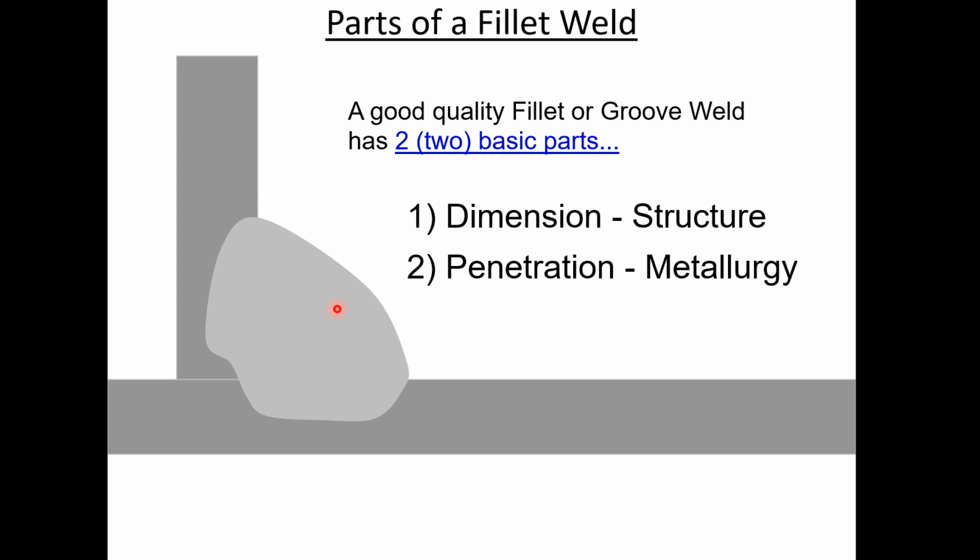I want everybody to understand that all these MIG welds, and we've heard of the term MIG welding, the proper term is gas metal arc welding, and this is the weld metal. You need to understand that this metal is not the same as this metal. We don't match these up when it comes to steels. The welded materials are much different in metallurgy than the base metals. And what we are counting on is penetration from this material, all this penetration, to homogenize, that is to mix with the weld and give it the strength that we need.